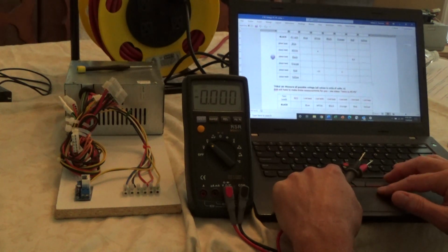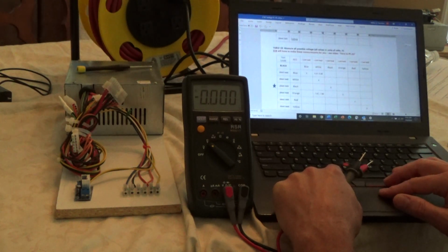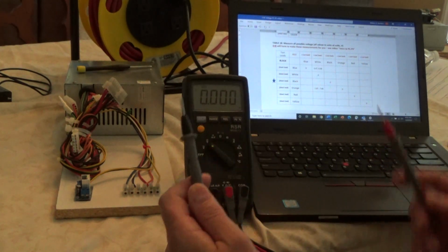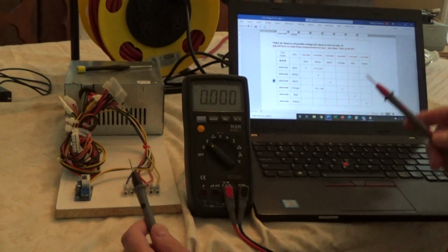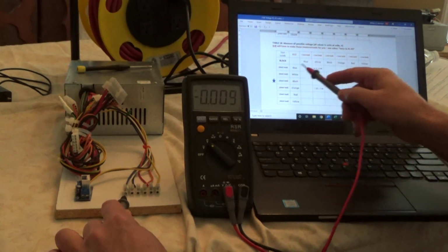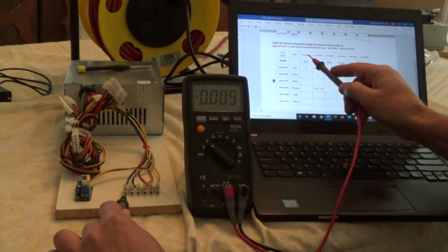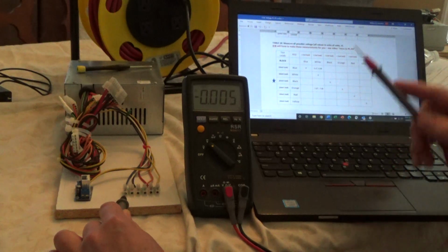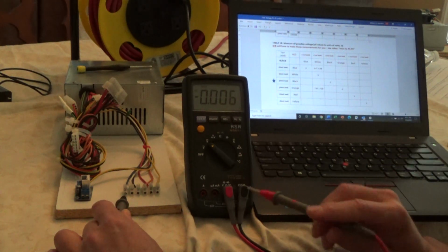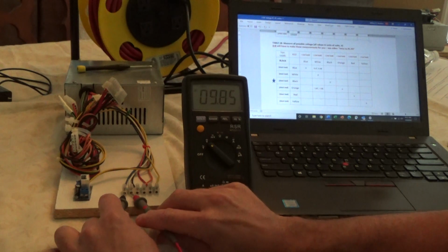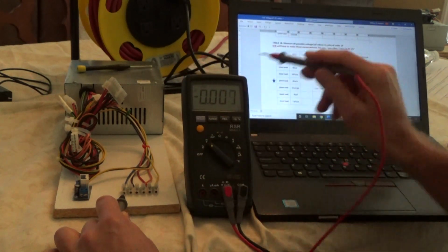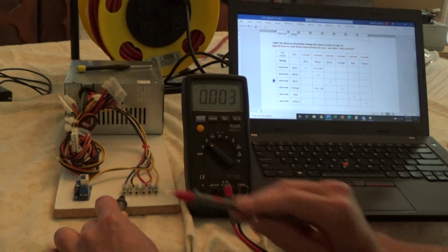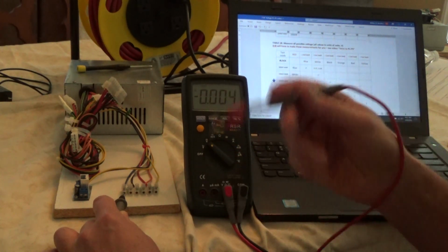Now, let me show you how I'm going to do this. This is very, very methodical. I've got everything laid out perfectly. We're going to take the black probe, and we're going to work this way in rows. If I put the black lead on blue, then I can take my red lead and go blue, white, black, orange, red, yellow, right? So I'll do this first one. Blue to blue is first, but that should be 0, and it is, basically. See that? 0. Why? Because there's no potential difference within its own rail.